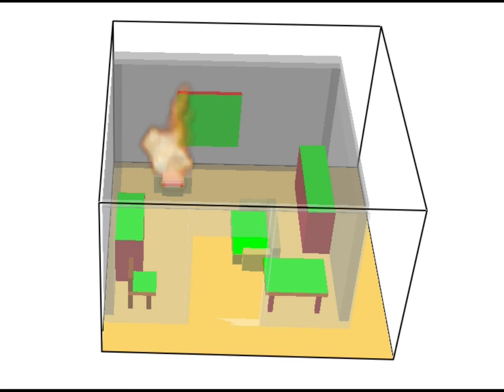Here we can continue to follow the growth of the fire from the ignition of the curtain onwards. With the help of CFD, we can switch off the smoke layer so that the flame spread is visible without obstruction. The surfaces in green are the surfaces that have been programmed through FDS to auto-ignite at a set temperature of 125 degrees Celsius.